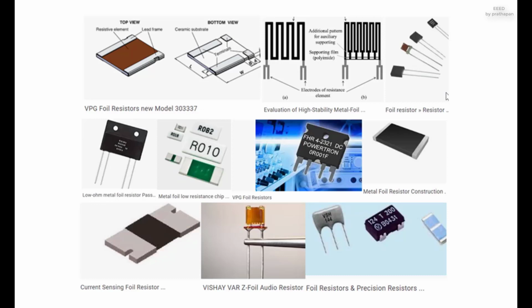Examples are chromal A and nichrome V, whose typical composition is 80 Ni and 20 Cr, with a melting point of 1420 degrees Celsius. When iron is added, the chromium-nickel alloy becomes more ductile. The nichrome and chromal C are examples of an alloy containing iron. The composition typical of nichrome is 60 Ni, 12 Cr, 26 Fe, 2 Mn, and chromal C, 64 Ni, 11 Cr, 25 Fe. The melting temperatures of these alloys are 1350 degrees and 1390 degrees Celsius, respectively.